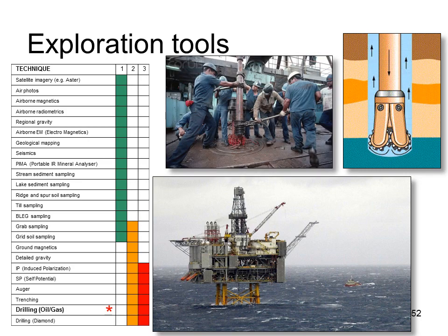Drill holes are large diameter, usually 5 to 36 inch in diameter. And it can attain a depth of up to 25,000 feet. They're usually fitted with steerable bits, which allow deviations of the hole to turn the hole in a certain direction or to flatten it to horizontal. Once a production well is drilled, the rig is replaced with a much simpler production platform.